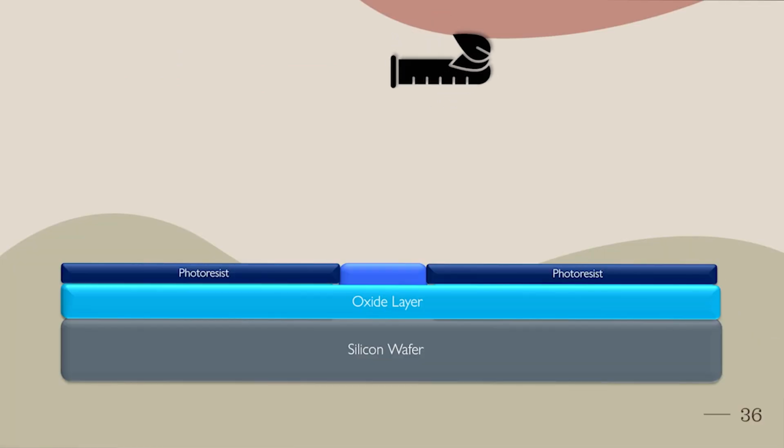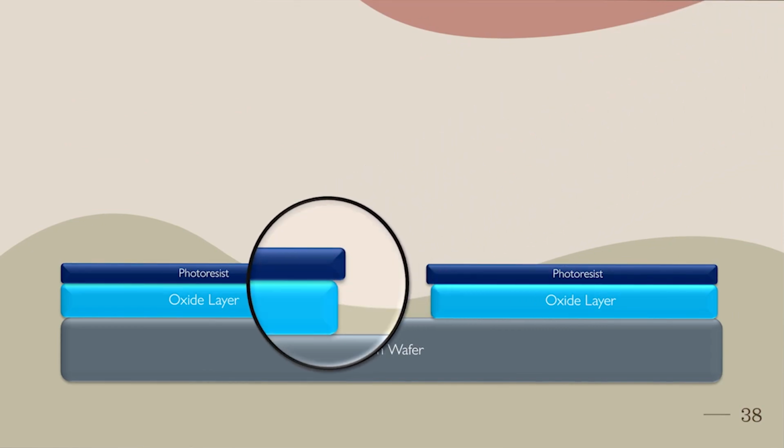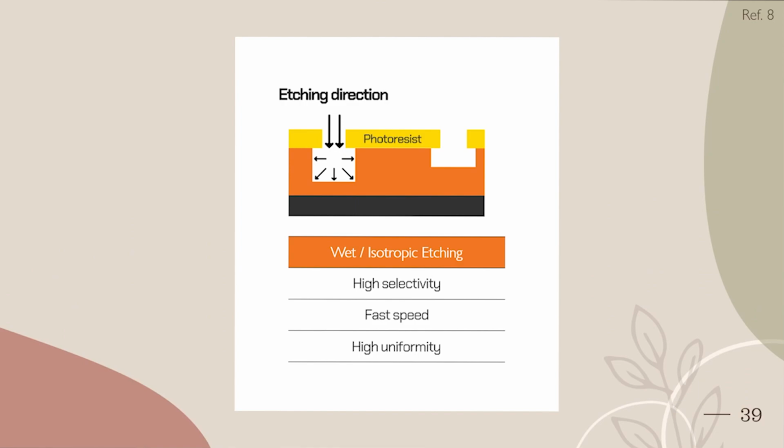Etching. New problems. If we just drop acid onto our photoresist layer, we'll get an uneven etch. I showed it earlier, but didn't highlight it. If we bring in our magnifying glass, we can see there's a little overhang here. This is a problem with wet or isotropic etching. It basically will go in and dissolve more than you want, because the fluid will flow, right?